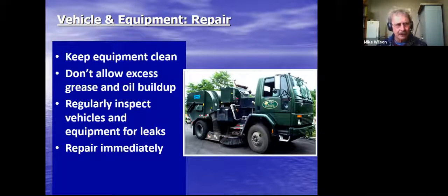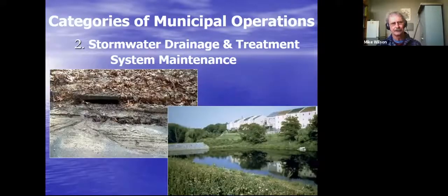In terms of repair and equipment, you want to keep your equipment clean. Don't allow excess grease and oil to build up on that equipment. It makes regular inspection much easier when you're looking for leaks if that equipment is clean. And if you do find a leak, repair it immediately. Do not allow it to leak into the ground. Go let your mechanic know.